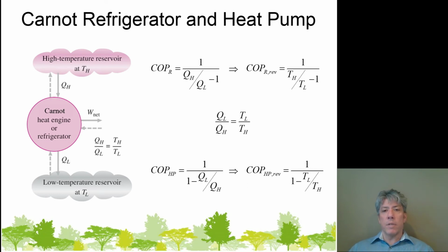And so all of this makes for a heat pump that is pretty efficient, and you feel like it's warm in the house because, yeah, you probably don't want to stand over the register. It's not all that warm when the heat pump is working, but it's warm enough you can tell, yeah, this is warm air coming out of the vent. So this is the way that we can determine the limits of operation. As a matter of fact, my heat pump has a SEER rating of either 16 or 18, I don't remember now. So it's not too bad. It's not as good as some of them today, but it's certainly not a slouch. Not near as bad as the heat pumps originally introduced.